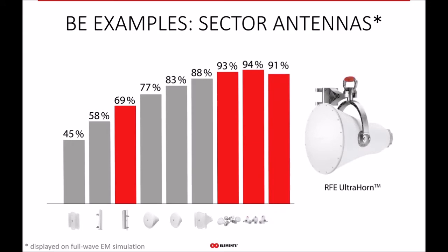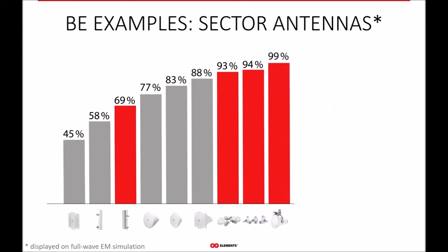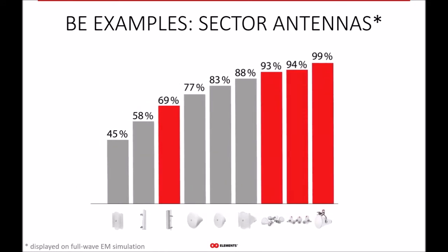So beam efficiency tells you everything about the side lobe performance, while front-to-back ratio or other parameters tell you almost nothing, really. Comparing front-to-back ratio as used in the WISP industry to beam efficiency is something like looking at the world through a keyhole, which would correspond to the front-to-back ratio, and being on top of a hill seeing the wide open space when you see everything crystal clear, which is the case of beam efficiency. The difference is simply vast.